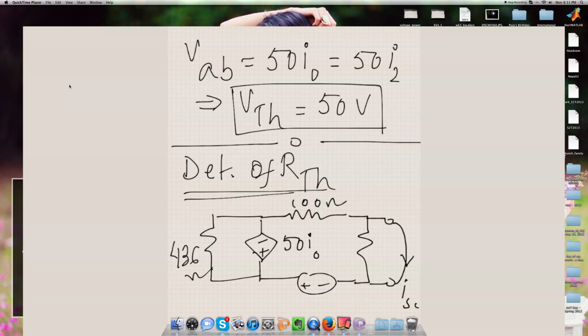So as we look at this parallel combination of 50 ohm and the short circuit path, we quickly realize that the 50 ohm will have no current flowing through it. There is no competition between the resistance, 50 ohm or whatever ohm, with a shorted path which has no resistance by definition.